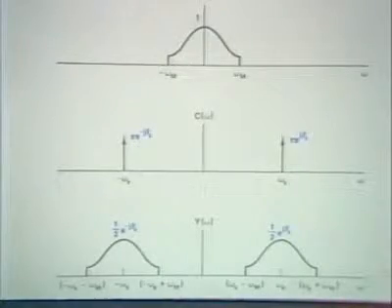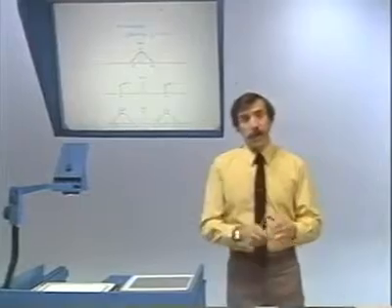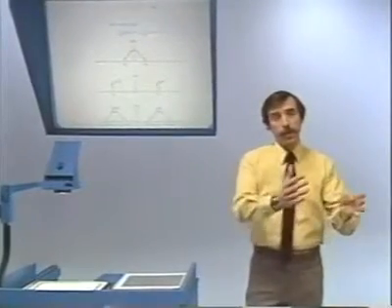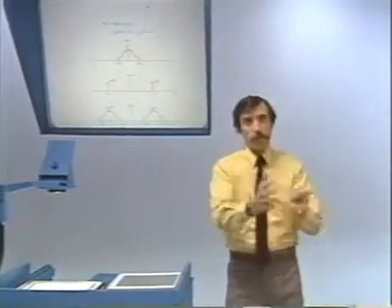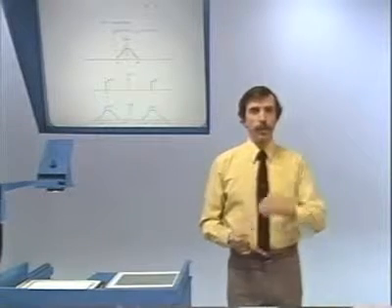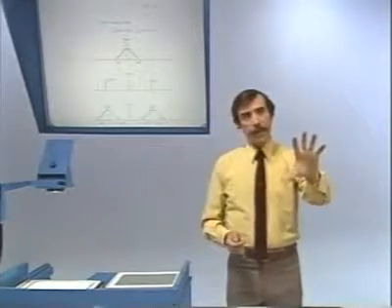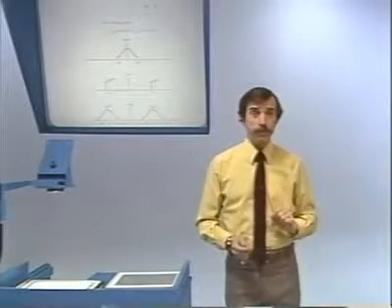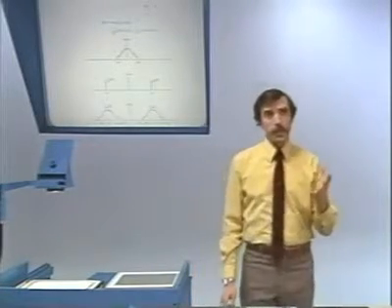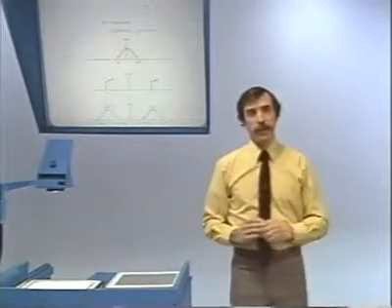Okay, well, now what's happened is that with a sinusoidal carrier, we've moved the spectrum to both plus omega c and minus omega c. And now if we want to get the original signal back again, what we would like to do somehow is move that spectrum back down to the origin. Now, in the case of a complex exponential, that was easy to do. We had shifted one up. We just shifted back down.